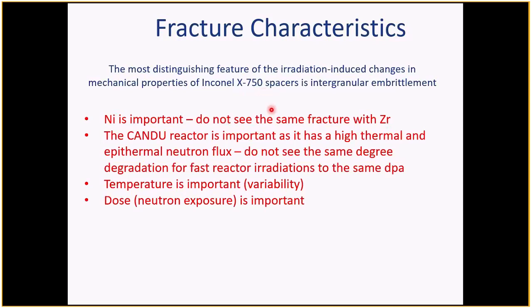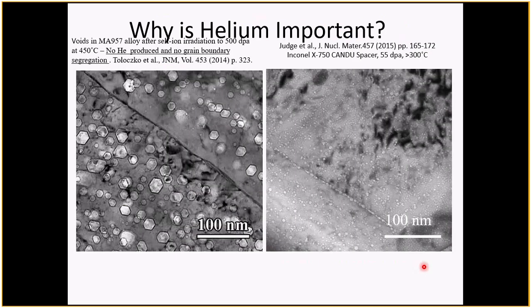There were specialized minor components in assemblies, like fuel assemblies, which weren't in the reactor for very long. But in the CANDU reactor, we have some critical components which are made from this, and they have to be in the reactor for the duration. And helium embrittlement is the big deal.